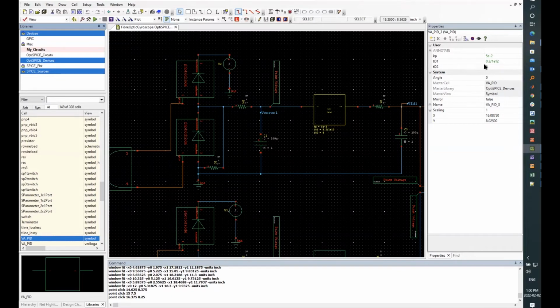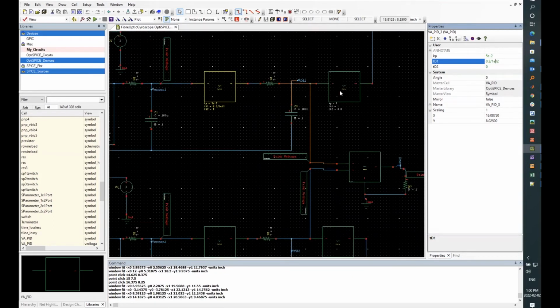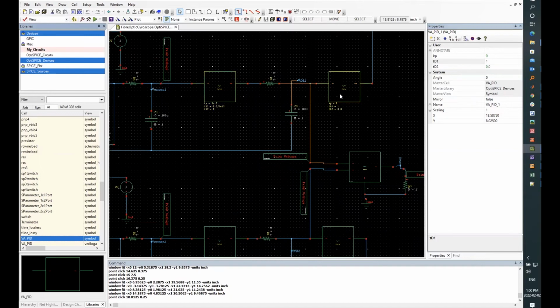You can see in the PID controller here we have the KP, the proportional, and the derivative. So we keep on tuning this proportional and the derivative values until a stable operation is achieved. And so the output of this PID is basically the shift in the angular frequency from the resonance. And then moving further, there's an output PID, which shows the shift in the angular frequency from the resonance, and the integrator.